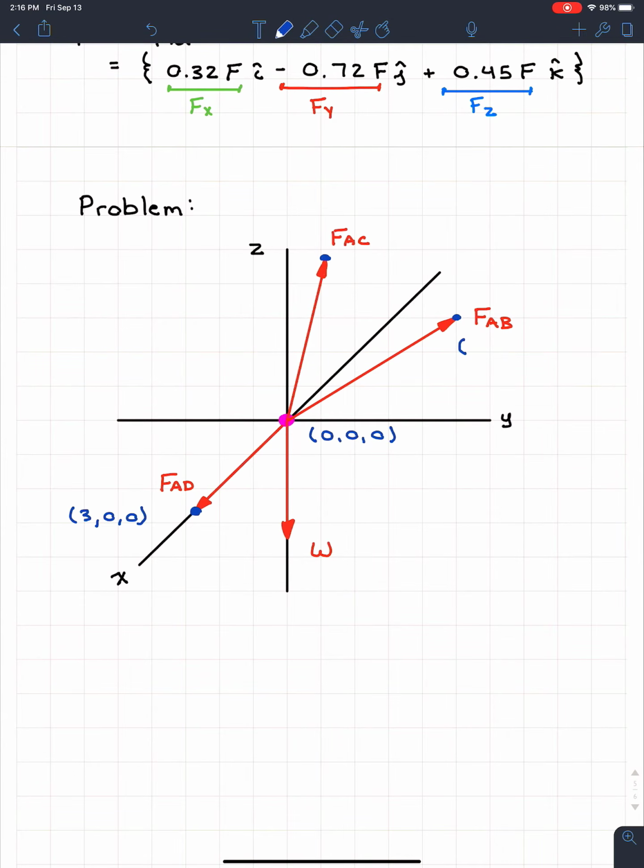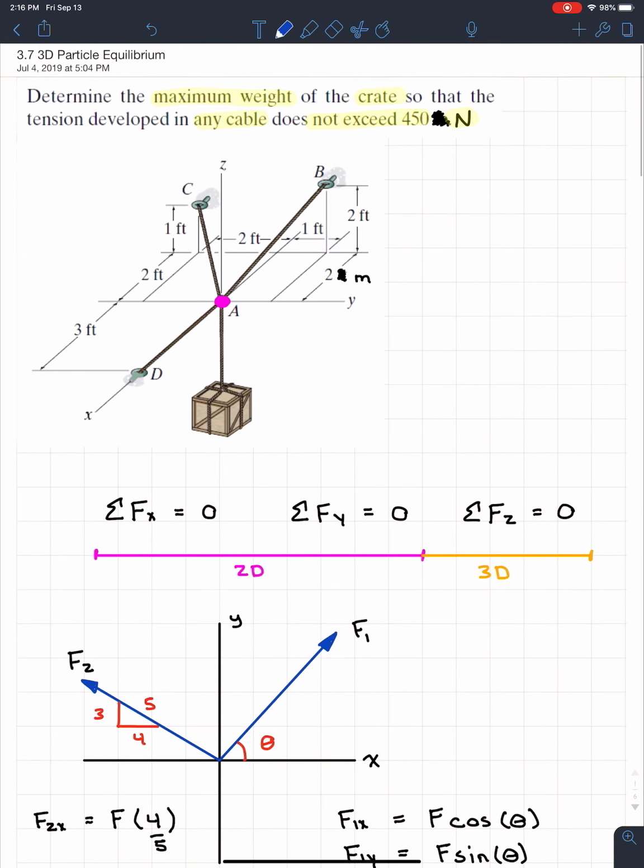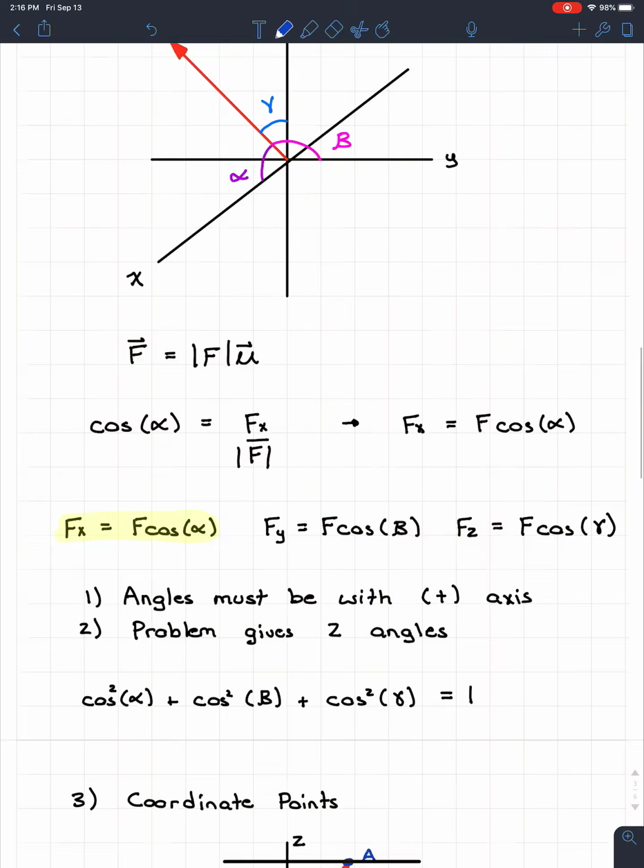And that's kind of nice because, again, the end goal of the free body diagram, you should be able to solve the question just by looking at your free body diagram. And if we actually have those coordinate points ready instead of all those dimensions that it has in the actual picture, we should be able to solve the problem much more quickly. So we're going to go up real quick and look at point B. And just looking at point B here, we're going to start off with the x. Well, we know it's actually 2 meters, but in the negative direction. And then the y is going to be 1 meter, and then the z is going to be 2 meters. So it's going to be -2, 1, and 0. -2, 1, and 2. See?